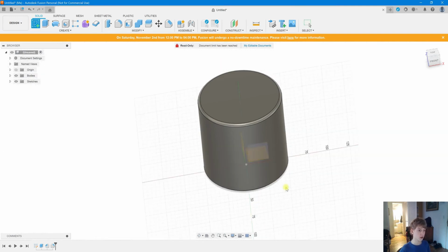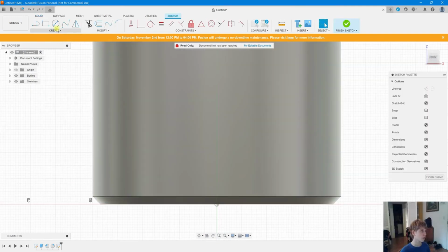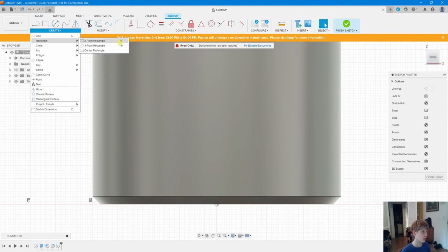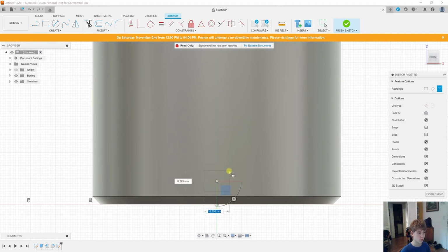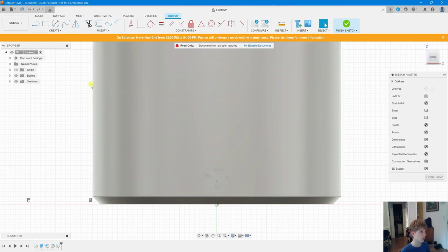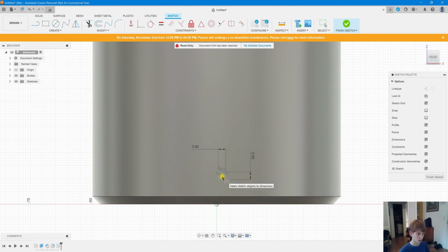Now let's create a sketch on this plane. Go to Create, select rectangle here, center rectangle, draw a rectangle from the center right here. Okay. For clarity, please set the size to 3 by 3 squares, making sure each side has 3 units. Then from the bottom, count up 4 units to determine the starting point. Alright. Select the centers and set them to be vertical.